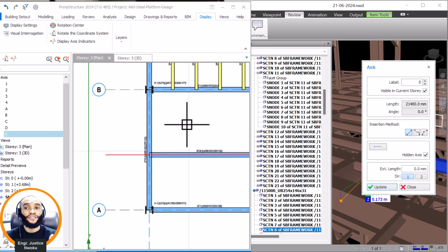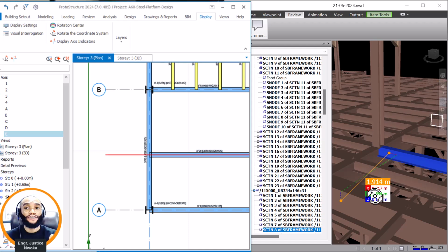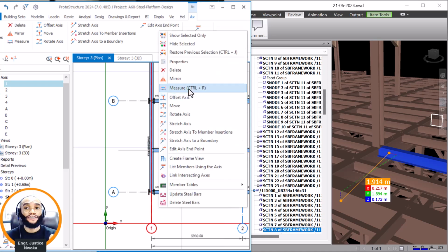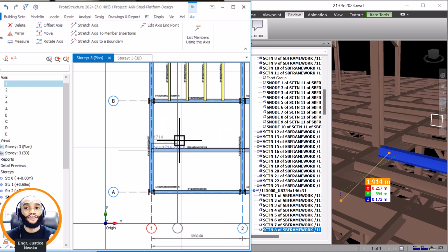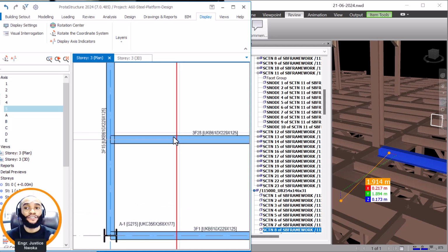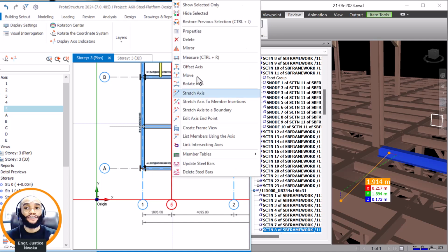That's fine. And then we now have to measure what? Measure 1895. So I'll come now, click on this point, right click here, on the grid line, offset, F2, then 1895. That's fine. And then press what? Enter key. So basically this is where the column actually is, this point here. Okay, that's fine. So we can now come now. Make here two ghost axis. Come here.